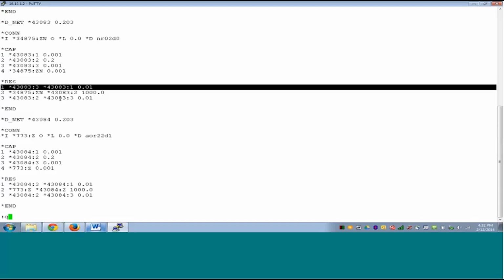You can even try to pick up a particular net and see. As an assignment, you can pick up a particular net in a netlist and try to search for that net's RC value in this file. This is a good assignment. That way you can understand better how the syntax works. I can do this here, but it's not that important, and it will take some time because SPEF is a big file and searching through it takes time. You can also do this kind of debugging in PrimeTime.